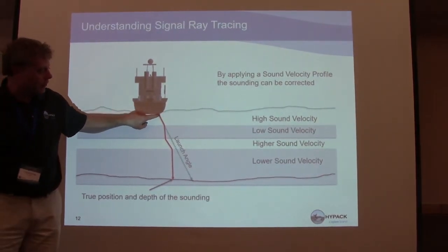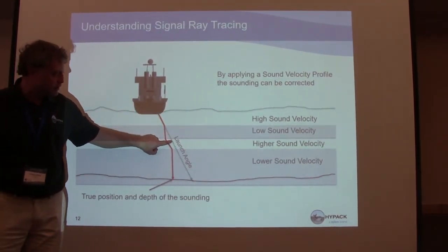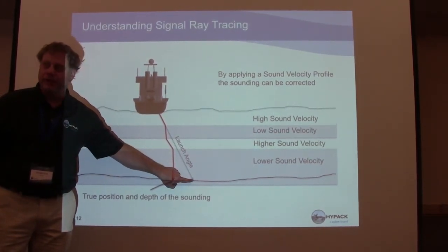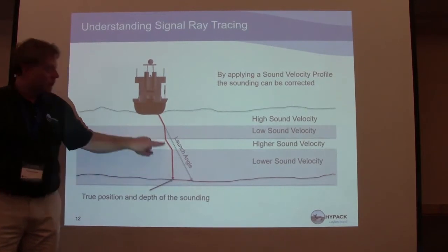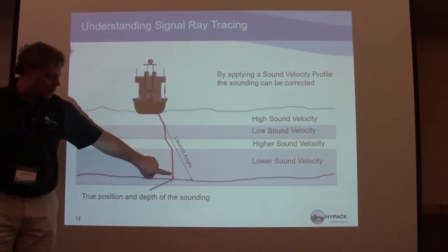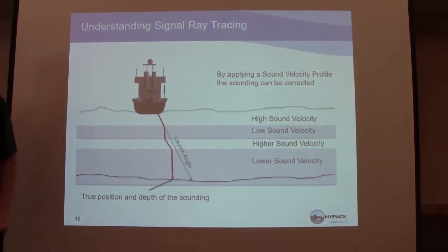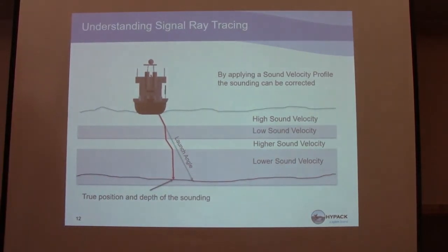So the launch angle of the ping, if we didn't consider sound velocity, would be this point down here. But with applying the sound velocity, now we can move the sounding to the right position based on the sound velocity file and ray trace and reposition the sounding where it needs to be.